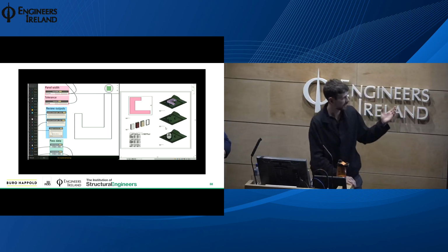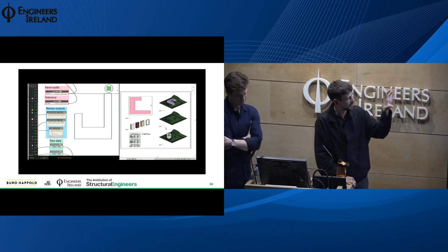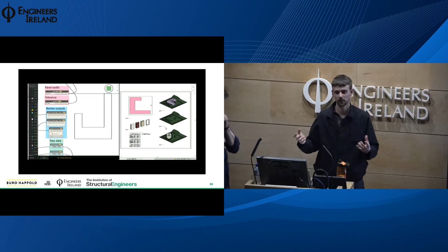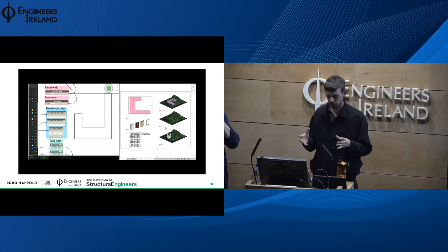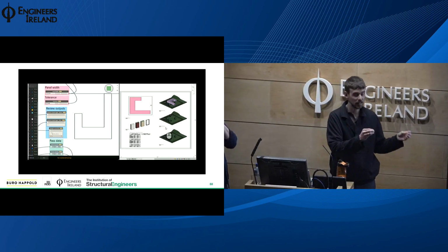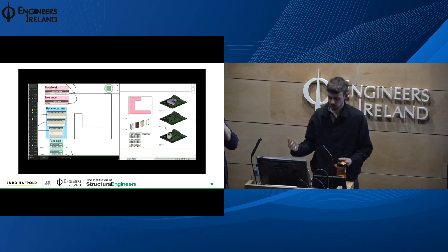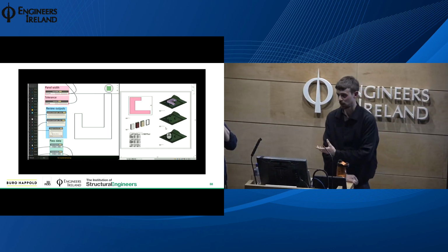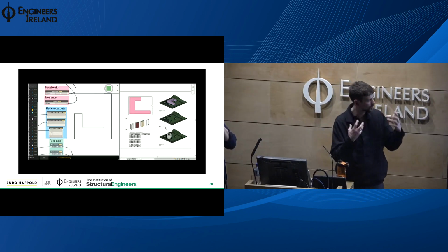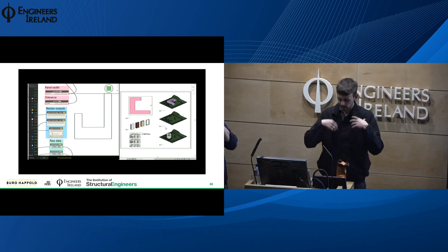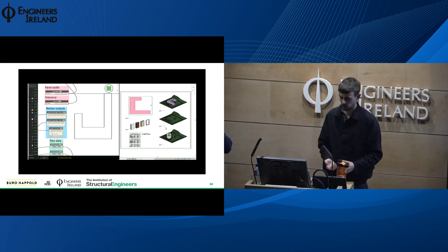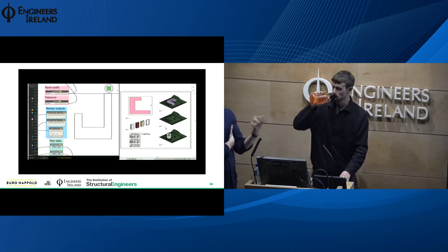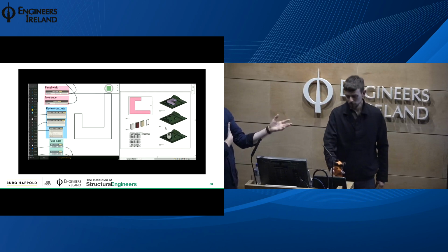In essence, what this looked like is once you'd manipulated this building massing to suit that regularized facade module, that building footprint would be pushed into the interdiscipline environment that we were talking about, so that Chris didn't have to jump into Dynamo to take the geometry out. I'm working in Dynamo for Revit, he was working in Grasshopper for Rhino. I pushed the geometry which represents the floor plate into Speckle, and then he can generate some grid options from that.